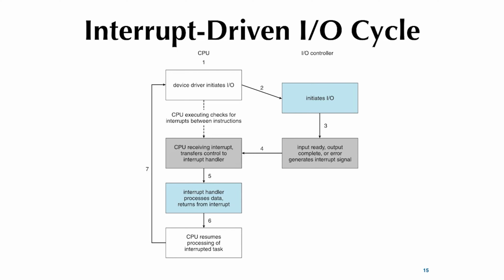Professor, if we have multiple devices sharing the same external interrupt, and we are going to serve with the ISR, what happens if the ISR is taking too long and another device is already coming? It's not going to be serviced, that device? Right. So if you wait too long, you could miss events. Yes. But a lot of times these processors are so much faster that this shouldn't be an issue.